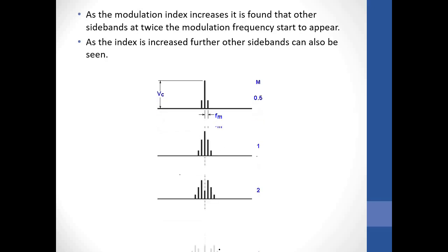So this is what we get. Because we're taking a modulus of the value, you can see the carrier is there. The first order is almost 0. We've got third order, fourth order, fifth, and sixth order side frequencies.